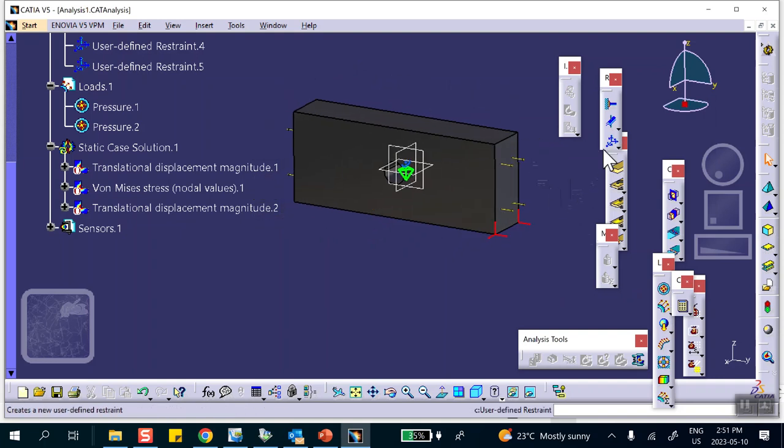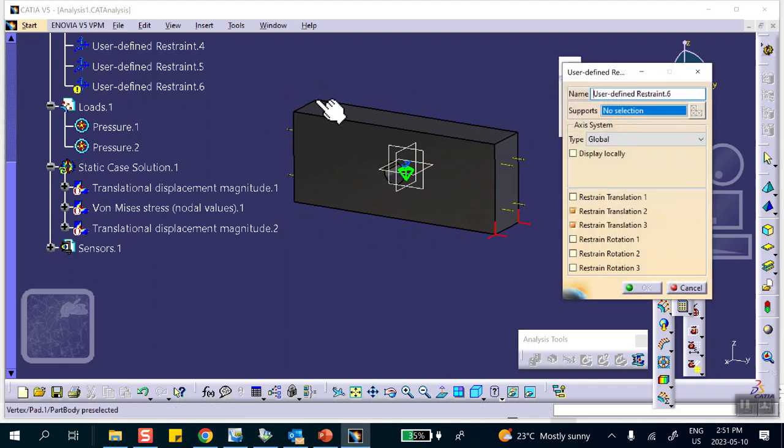Okay, no problem. And a third point, this point, for example, these are not going to be random anymore. You have to think about it. This point cannot move in the direction Z. This will take away the rigid body motion. This will take away the ability to float. This will allow it to rotate about that line, and this will prevent that rotation.